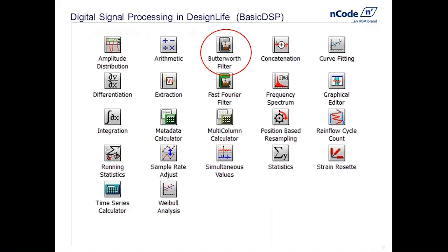In terms of looking at the actual frequency content, there's another glyph called Frequency Spectrum that'll bring in a time history and output an amplitude or power spectral density. So I can look at the frequency content of my time histories. Again, I may be trying to make decisions on whether I need to look at my model in terms of dynamics, or I can get away with quasi-statics.